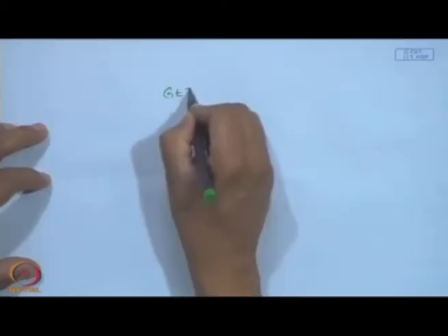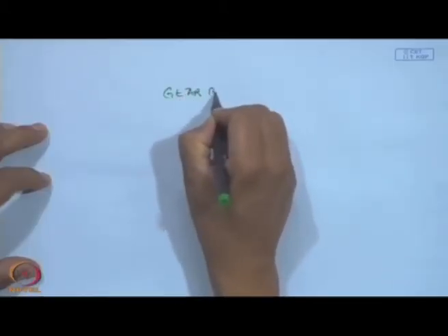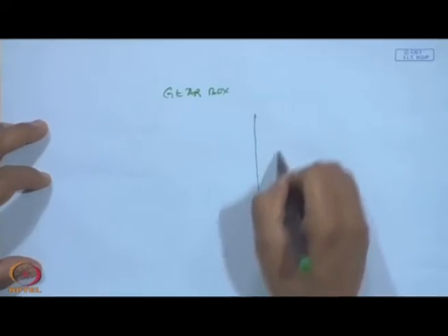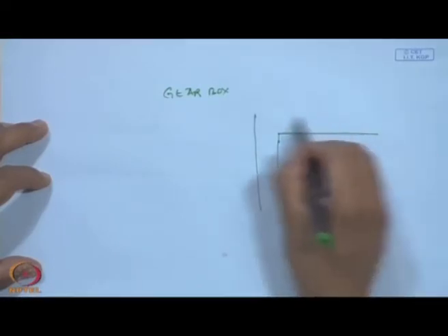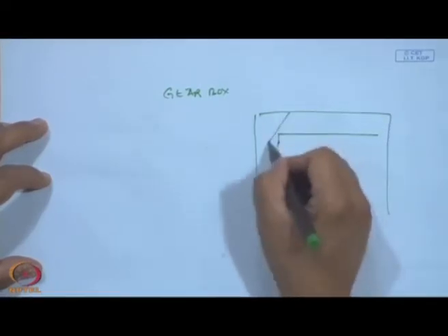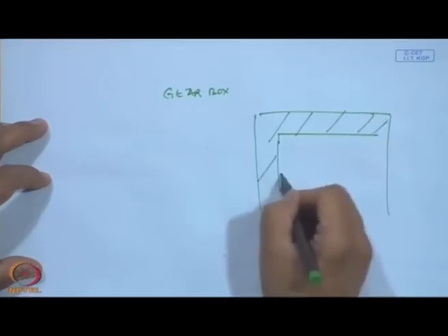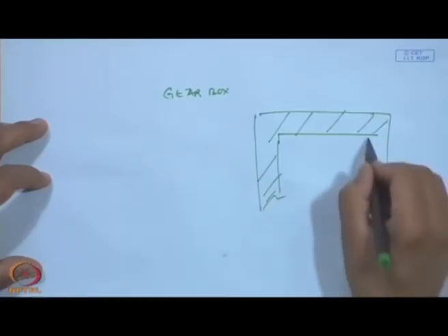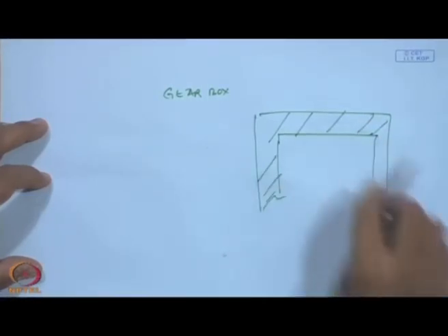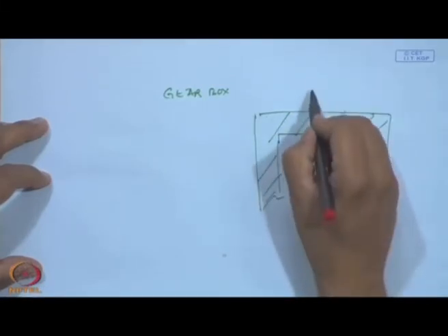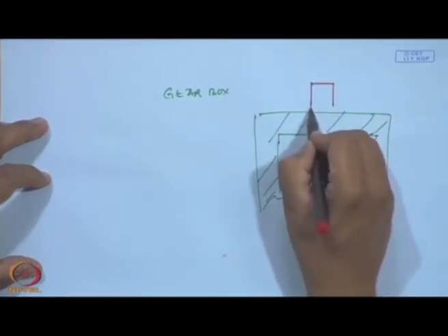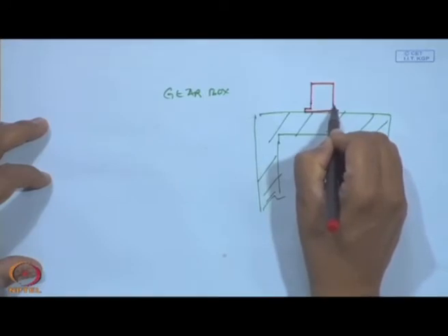Everywhere there is vibration. How do you measure that? Okay. Obviously, on a gearbox casing, I can mount my accelerometer many ways.